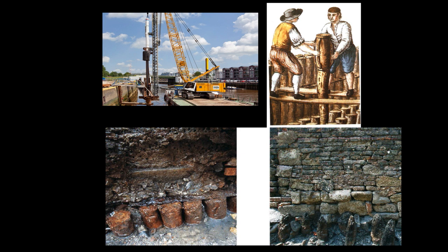Now, they came to discover that some types of trees are more resistant to water infiltration than others. And so by carefully selecting the wood that you use, you have a better chance of having long-lived foundations. But in addition, if the logs are pounded into mud that is created by salt water, the salt content of the water, as well as the fact that there is very little oxygen that actually gets to these logs, means that the logs are going to decay much slower than they would if they were actually exposed to oxygen.